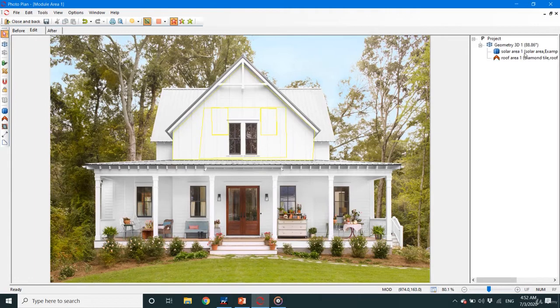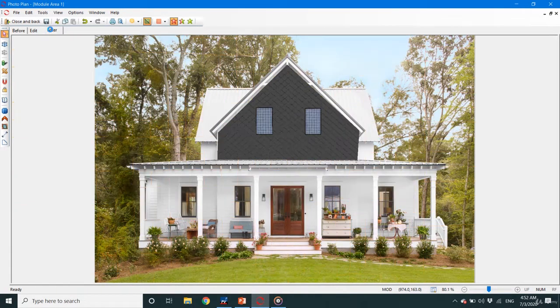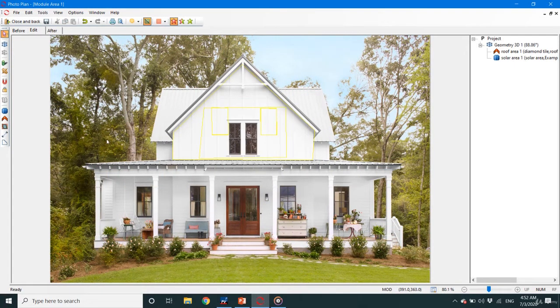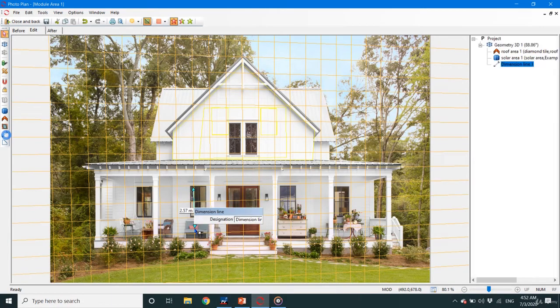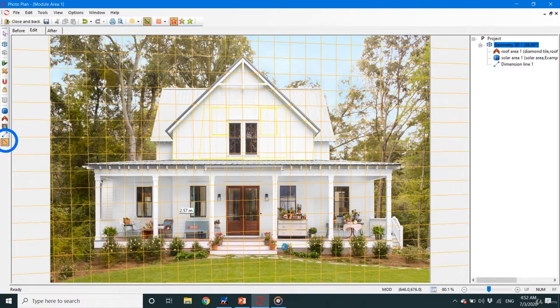Make the roof under the panel and you will see them. You can see the panels of the modules now. PVSol has made calculations and predictions of all the dimensions. You can measure the dimensions by clicking here, or measure an area or a polyline by clicking here.